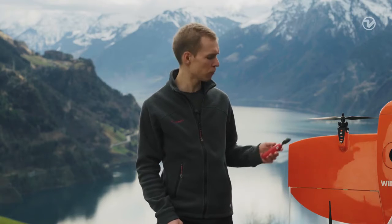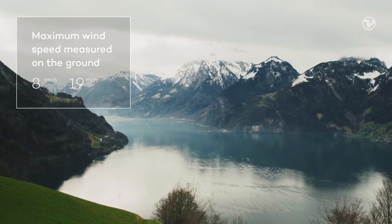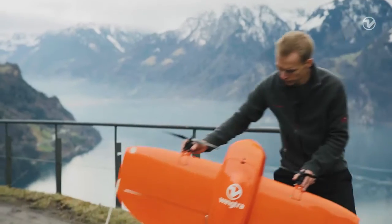And then there is wind, which is a key factor for drone flying. So we have to measure the wind speed on ground before taking off. Right now, we have 0 meters per second of wind, which is of course safe to fly. WingtraOne can handle wind speed on ground up to 8 meters per second. Let's move the drone for takeoff and look into flight planning.